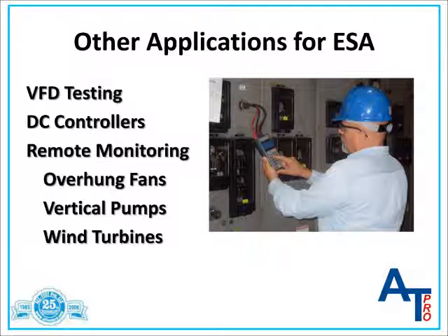While MVA has been around for over 70 years, ESA is relatively new to the predictive maintenance market, but it is proving to be one of the most useful technologies for performing the all-important detection portion of the predictive maintenance program. Not only will it identify all of the mechanical faults that MVA does, but it also performs a power quality survey to determine the condition of the power feeding the motor system.